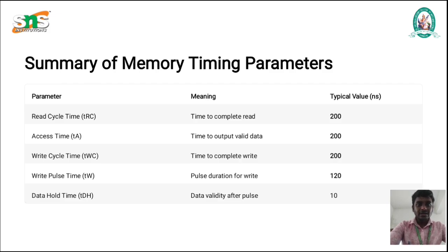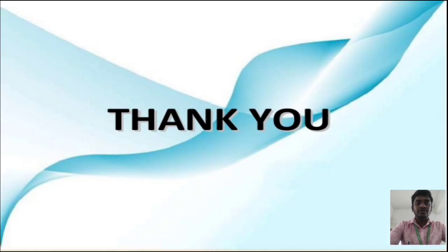Write pulse time is the pulse duration for write, 120 nanoseconds. Data hold time is approximately 0 nanoseconds, maybe plus or minus 10 nanoseconds. It means the data validity after the pulse: how long it will hold the data after the pulse, approximately 10 nanoseconds.